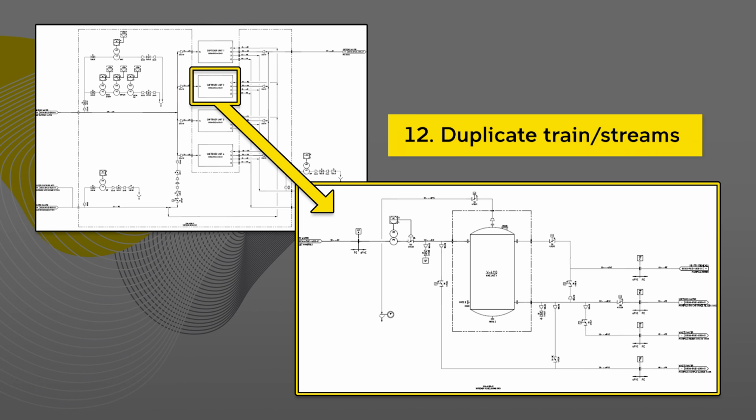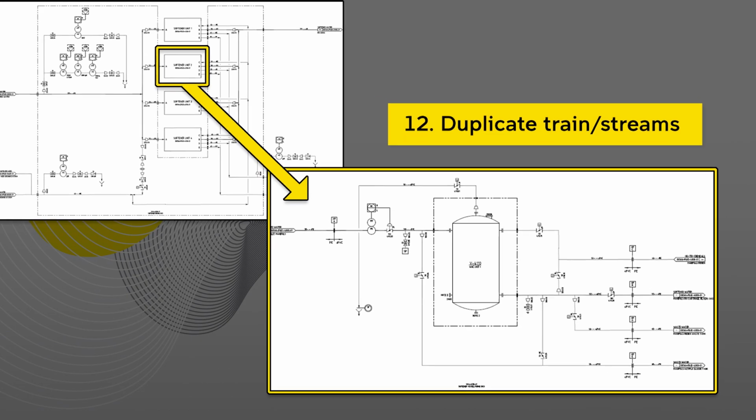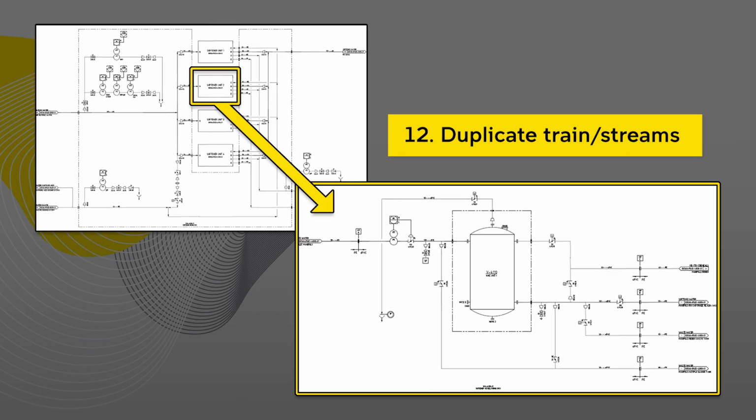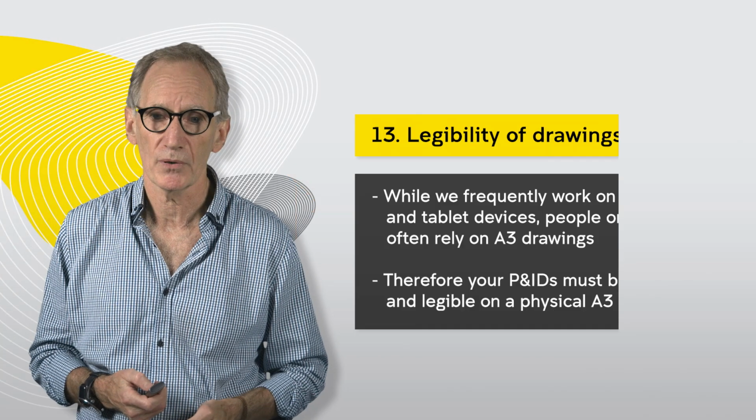And what this does is it helps communicate the overall design, because on that first drawing you can see the overall flow through the whole system. You see the flow coming in from the left, you see it gets split across a bank of pieces of equipment, and then the flow comes together again and leaves. Now what's in those boxes? Let's look in detail at the next drawing, and you can see that information. You can imagine how crowded that first drawing would be if we tried to put all that information in every one of those boxes. It would be impossible. It would be illegible. Which leads me on to another point.